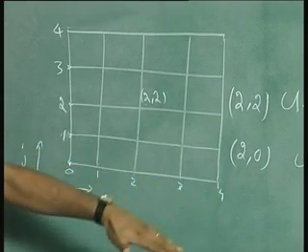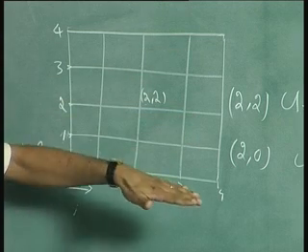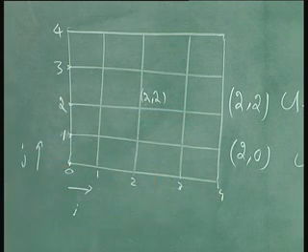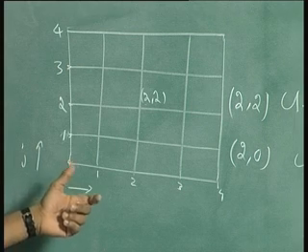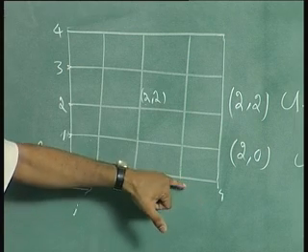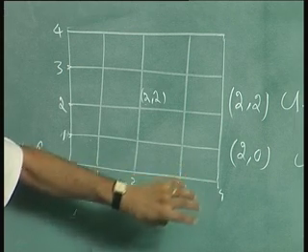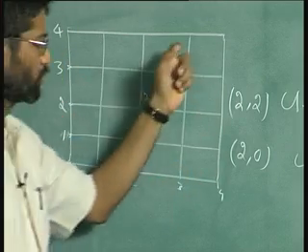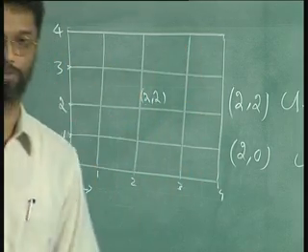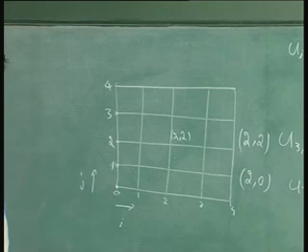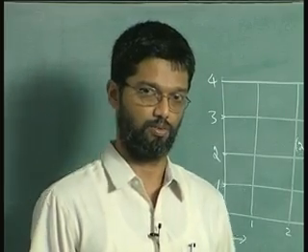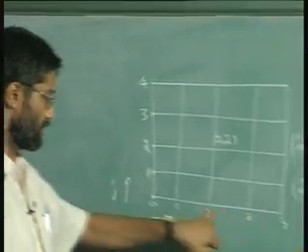So in our example of temperature distribution, it is specified what the temperature at these boundary nodes is. That's one case. Another case is that we don't know the temperature there, but we know the derivative of the temperature at that boundary. So there are two specific examples which we should be looking at. Let's look at the first example, where the boundary conditions are specified in terms of the temperature. So we are given the temperature at these boundary points.